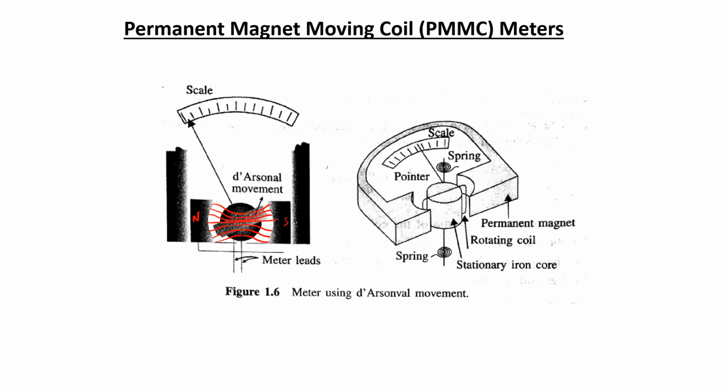Whatever the movement, according to the curvature of the poles, the moving coil will always be aligned along the radius of the curved pole face. So the magnetic flux lines are supposed to enter or cut the edge of the moving coil perpendicularly or almost perpendicularly, resulting in the maximum possible torque experienced by the moving coil.